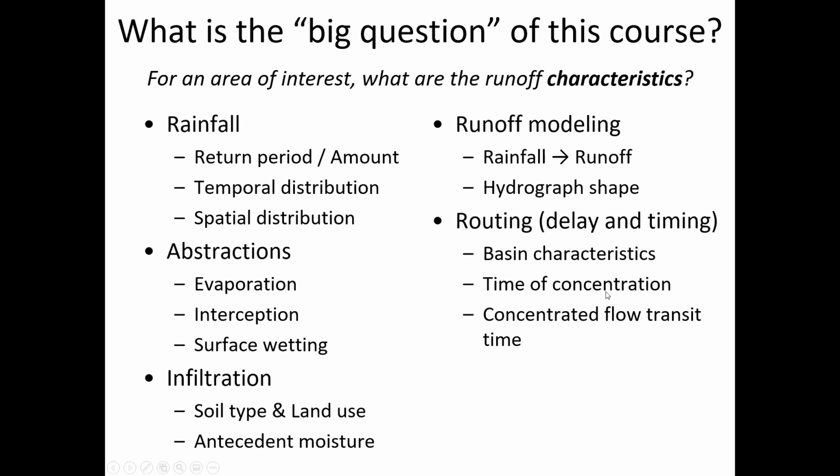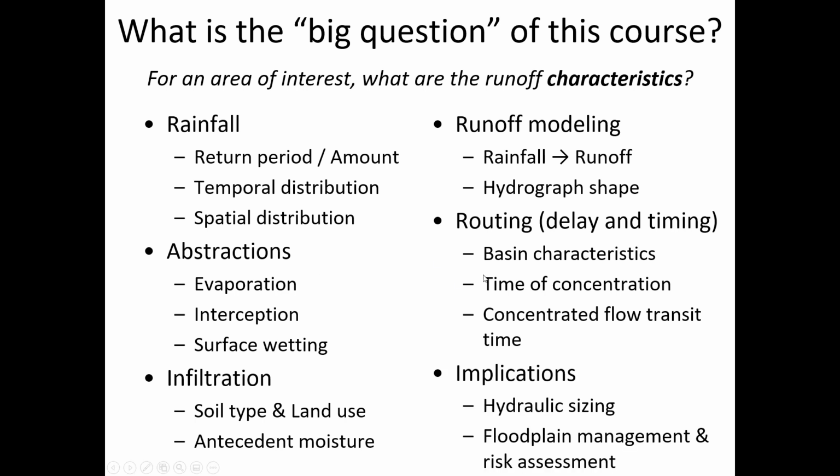So the time of concentration, not just for surface flow, but also as the water is going through the streams that may form. So the delay of the hydrograph as it travels through the watershed is part of what we'll calculate in those computerized models. And then towards the end of the semester, we're going to look at some risk assessment issues. And when you prevent a certain amount of flooding, how much economic value there is in preventing that flooding.